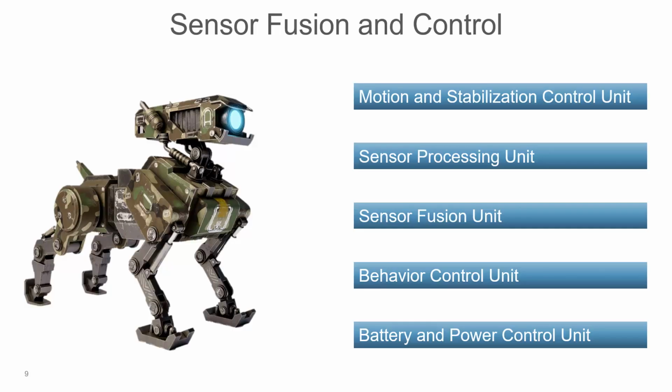Another example is this security robot. It has similar modules like the drone, and a hard real-time loop is critical to ensure the robot can move balanced in the real-world environment and under different conditions. I have seen examples where not meeting the deadline for the control loop results in the robots losing their balance or not meeting the mission criteria.